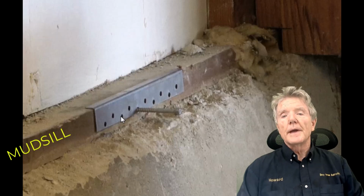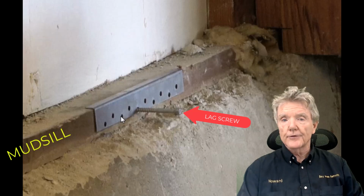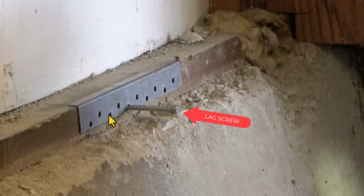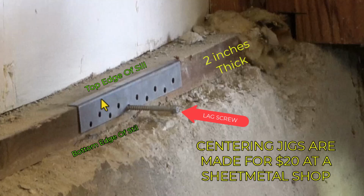The first thing we do is make sure that the lag screws go straight in the center of the mud sill as the manufacturer requires. And we do that with a foundation anchor centering tool, and I'm going to show you how we work with that right now. Now we need to get this lag screw right in the center of the sill, or at least it's got to be a minimum of 3/4 of an inch from this edge and 3/4 of an inch from this edge. Now fortunately in this case we have a sill that is 2 inches thick. So what we've done is we put some holes in this jig such that the hole is exactly 1 inch from the top edge of the sill and exactly 1 inch from the bottom of the sill.